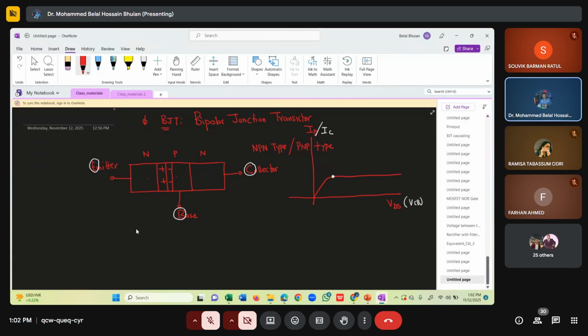Similarly, the N-type collector and the P-type base on the other side make another PN junction, so we have another depletion region, again with exposed boron ions and positively charged phosphorus ions. This junction is called the emitter to base junction, and the other junction is called the collector to base junction.